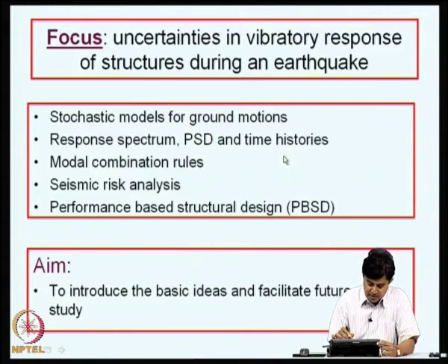So, we will investigate what is the relationship between these three alternative ways of specifying earthquake ground motions. Then there are issues about using response spectrum based methods for analyzing multi-degree freedom systems, and that lead to questions on what are known as modal combination rules. This again will be one of the topics that we will discuss.